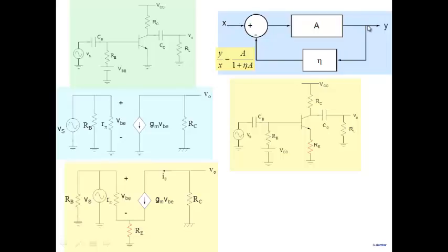What do I have to do? I have to take Y, sample the output, multiply it by something, and then subtract it from the input, right? My Y is the small collector current, IC. What am I multiplying with? RE. IC comes in through RE, and the drop here subtracts from the input. Input was Vs, and the drop is subtracting from it. Input earlier was dropping entirely here. Now it is subtracting from it. That's how negative feedback is operating.